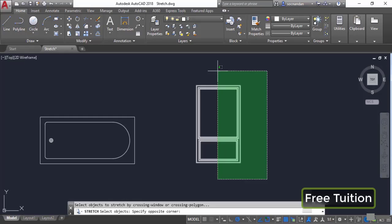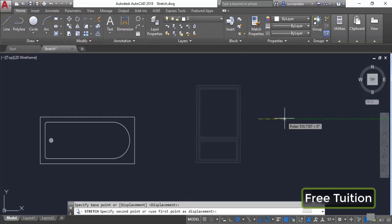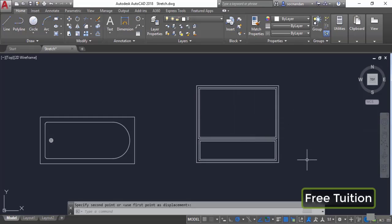So in this case all of these segments are partially inside and partially outside, so only the length of these segments will change. So now press enter, click at a point and stretch it just like this. So in this way we can use a stretch tool in AutoCAD to change the shape of geometries or stretch them in a particular way.